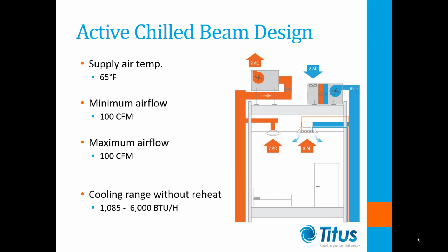Occupant comfort is also improved as the chill beam is providing constant volume air at a slightly warmer temperature than an all-air system during cooling, so is less likely to cause cold spots and drafts. One important point to note is that while the primary air can be delivered to the space at 65 degrees, it must be suitably dehumidified first to offset the latent load in the room, so is typically supplied at 56 grains or less.